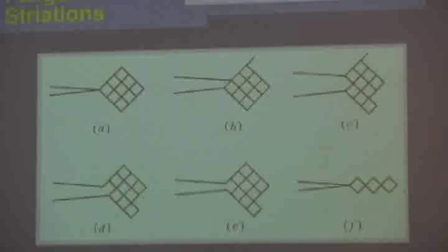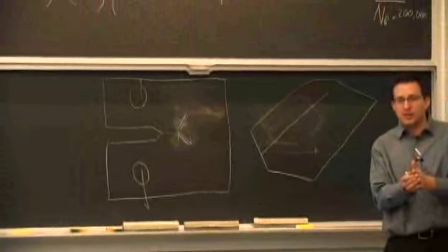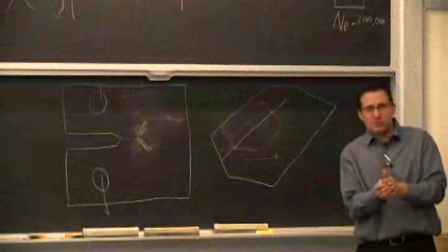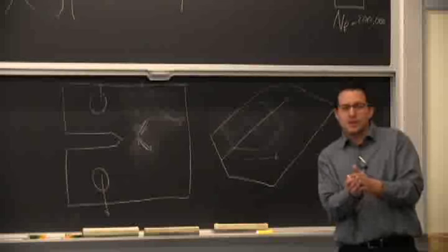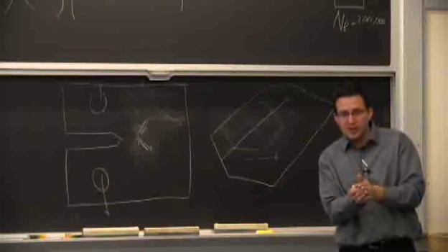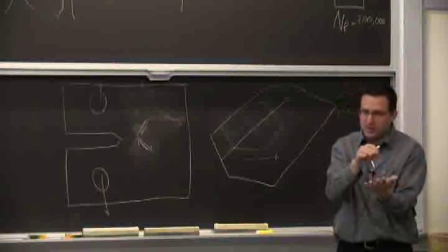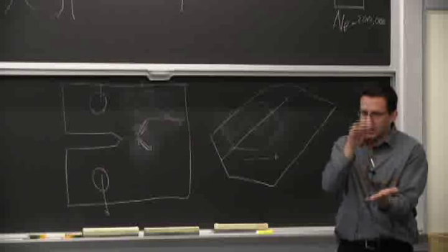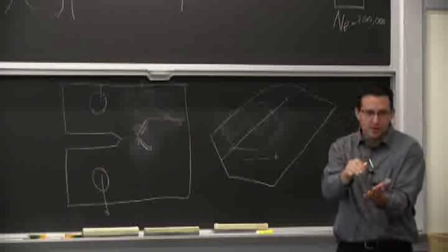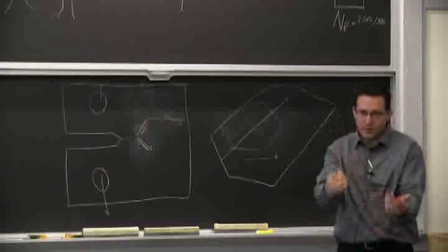And what happens sometimes is the crack tip here will shear some this way. And the consequence of that is you'll start rubbing between the two fracture surfaces you created. You could probably think of it this way. It's a good thing, because now when the crack is trying to close, there's something stopping it. So it gets less of an amplitude of deformation in the plastic zone, and you don't have as much growth.